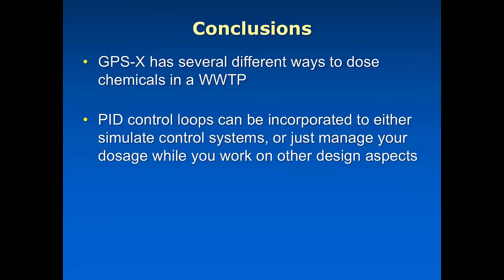Okay, so just concluding, GPSX has several different ways to set up and dose chemicals for various types of processes depending on what you're doing, and a number of different PID controllers that can be incorporated, and you need to make sure you've got your tuning set up properly. Sometimes those controllers will actually be the focus of what you're trying to do as part of your optimization, or maybe you just want to change the degree of freedom in your design. Just let that thing dose whatever it needs to dose in order to get the job done, and then I'll just keep an eye on how much it's telling me I need. And that's obviously one of the most useful aspects when you're using GPSX for design.